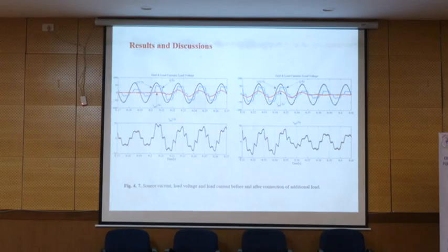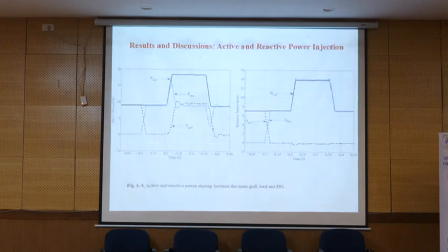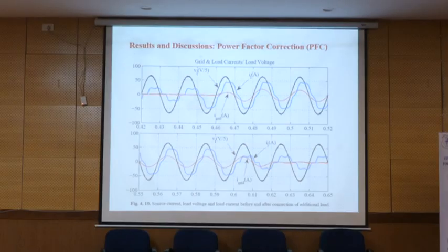Grid current. Grid current, excellent. Yeah, we have actually this grid current here. So you see that grid current is sinusoidal. Okay? Grid current is sinusoidal. And one other important thing is that when you go here, you see that grid current is in phase with the voltage. Look at, this is the voltage, this is the current. And the voltage and current are in phase.